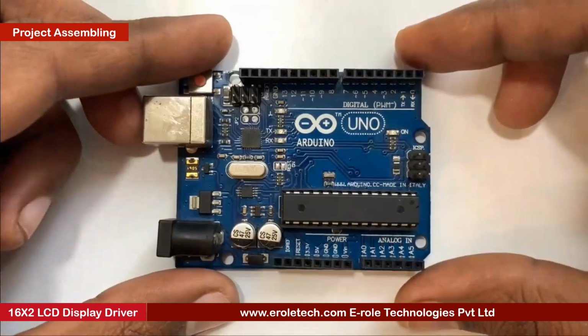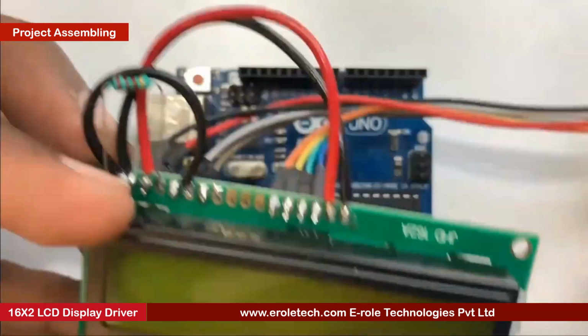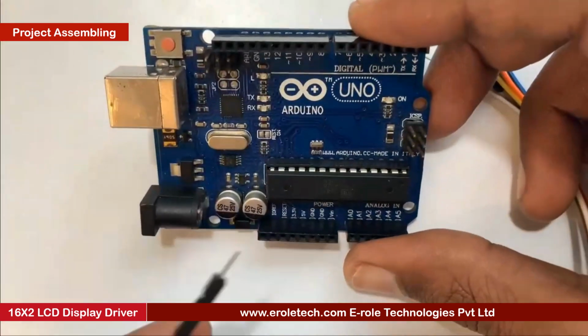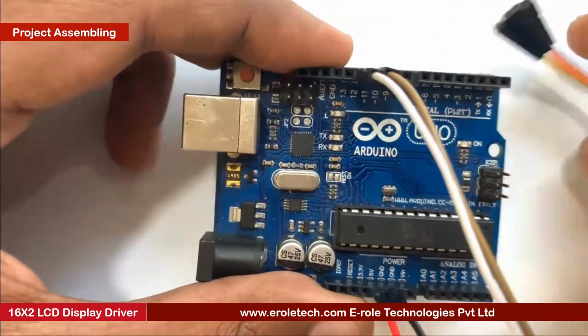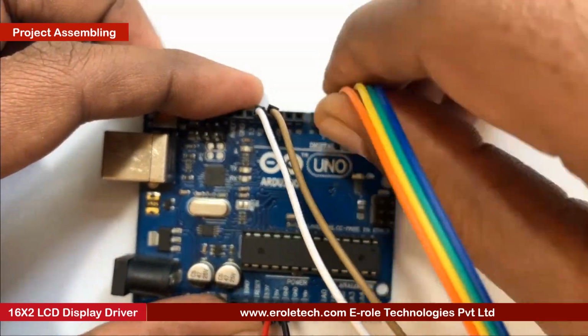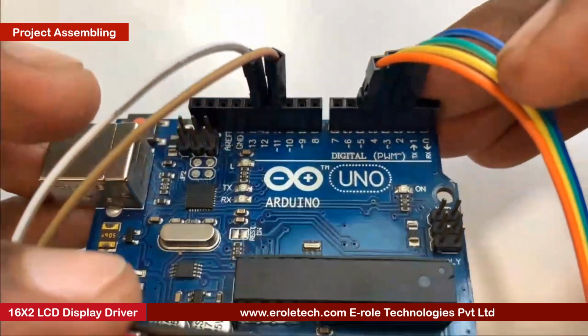Now we will connect the LCD display with our Arduino hardware board. Connect the red wire with the 5-volt pin, and the black wire with the ground pin. Now connect white, brown, orange, yellow, green, and blue wires with pin number 12, 11, 5, 4, 3, and 2 of Arduino respectively.